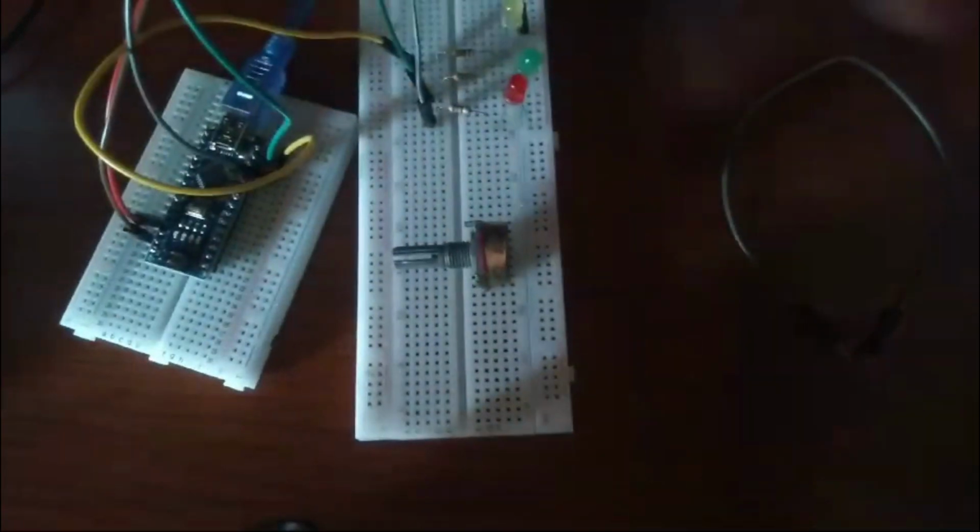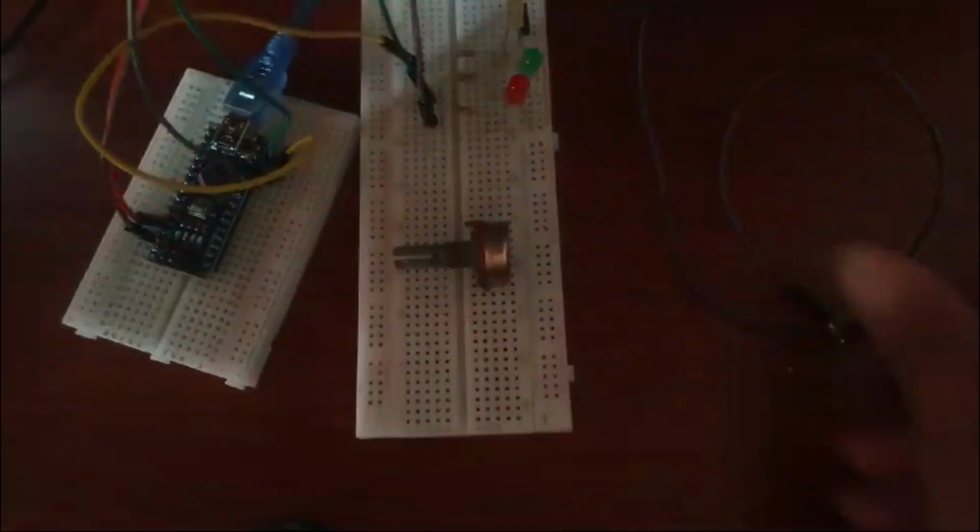So of the pins, you have to connect one of the extreme pins to the positive. Yes, as you can watch here, we have to connect it to the positive. So you have to ensure that the position of the cables and the potentiometer is good for you, right? So we're going to connect the first extreme to the positive. It's very important that in this type of protoboard you connect the positive and the negative to the same bus